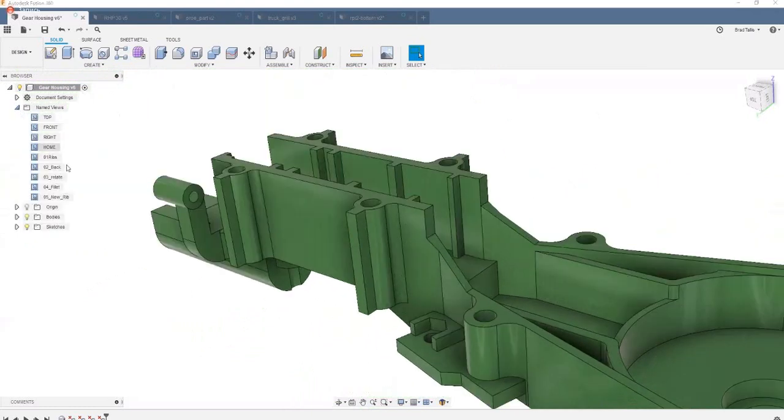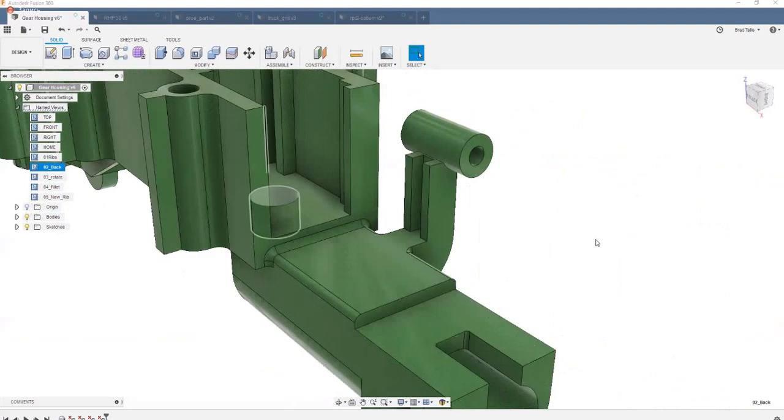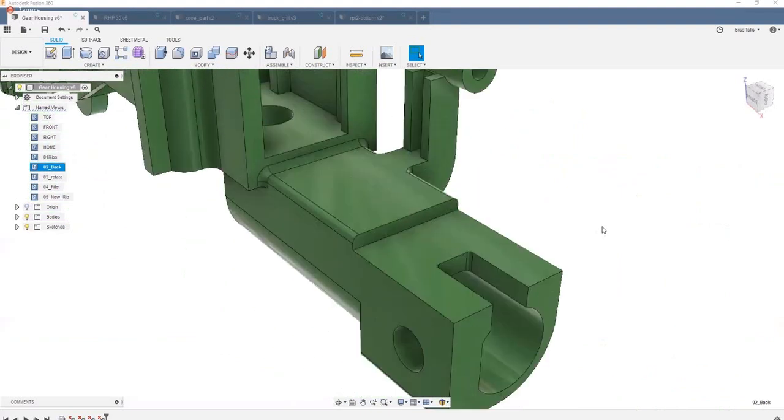Okay, let's keep going on here. So here's another example, and I've seen this a lot, where you can see there's this cutout right here, and the fillets just kind of end, and there's no fillet on the end. It almost seems like this might have been a mistake, like something machined this away, and the engineer didn't notice it until it's way too late. And this shelf is supposed to be at the same height as this shelf up here, and these fillets are supposed to go all the way along the edges, etc.